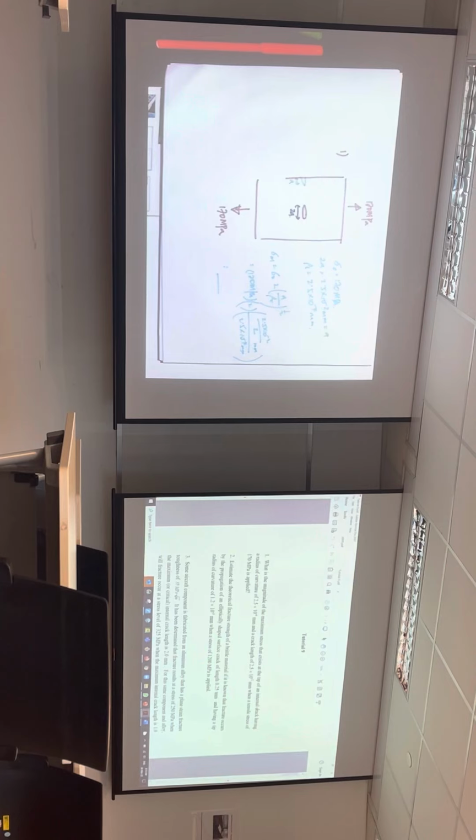When the curvature goes down, the sigma m value goes down. So for ductile material, that's why we say the materials tend to be stable in terms of the crack. Whereas with a brittle material, once a crack moves, you just go right through. In other words, if one day you can find a plate where the crack goes halfway and then stops, give it to me.